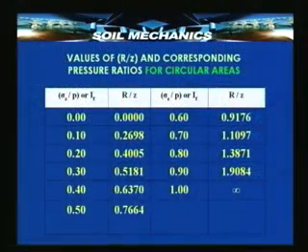generalizing the problem of computing stresses, and this generalization would eventually lead us to compute stresses not only beneath circular areas for which this table has been evolved, but also areas which are either rectangular or any, for that matter, any arbitrarily shaped area. We shall come back to this second table later on in a short while. It is the first table where we have Z by R versus IF that we shall be using for computing stresses below circular loaded areas.